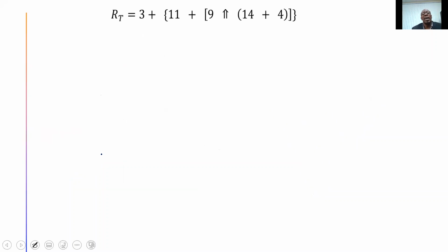So just by looking at the equation, we already know that the total resistance is 20 ohms. For a voltage of 120 volts, we know that I, which would be the current from the source, would be equal to 120 over 20, which gives us 6 amperes.